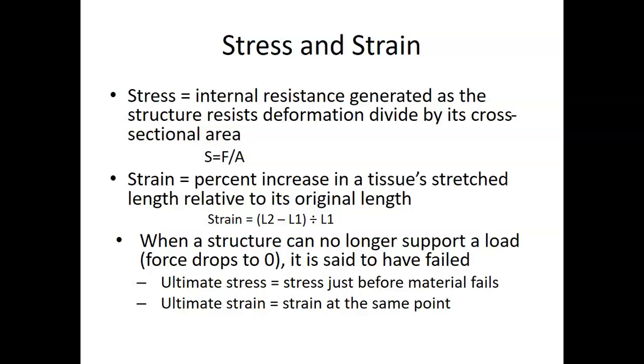So if you think about a TheraBand versus a rope, if I pull on a TheraBand, it's much less stiff than a rope would be. If I pull on a TheraBand, I have some give. If I pull on a rope, I have very little. So there's very little change in the length with the rope. So it's a lower strain to the same stress. Does that help?